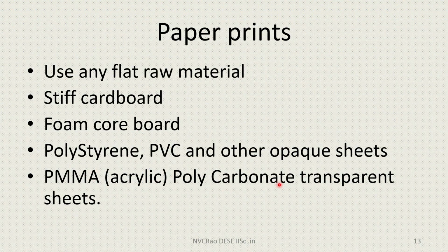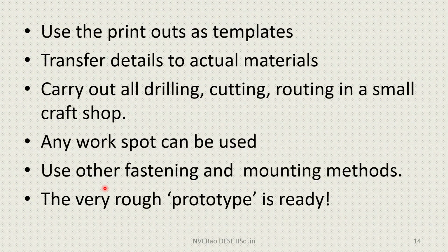Now we have two other things. One is these are all transparent sheets. Use the printout as a template, again recapitulating, transfer it to materials, cut out, do the drilling, cutting, routing in a small craft shop or any workspot, add other fastening, and a very rough prototype is ready.